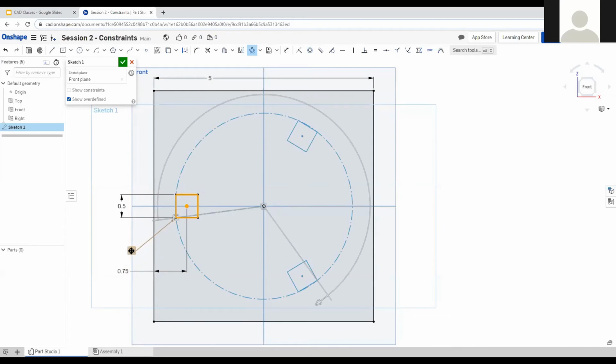So you may notice some similarities to the linear pattern. For example, there's this small square here, which will let me change where the center is, similar to the way that you can change the angle of a pattern. And then there's also this here, so I can change the rotation. Say I only want that to go out to there. I can set this to 180. I have 3 copies of this square. They're all going around.